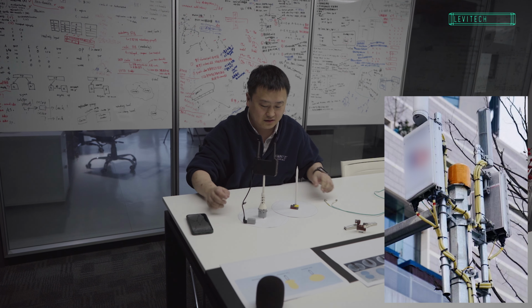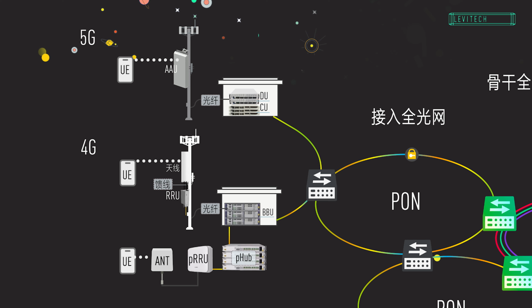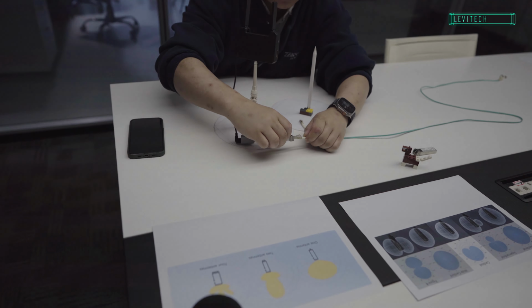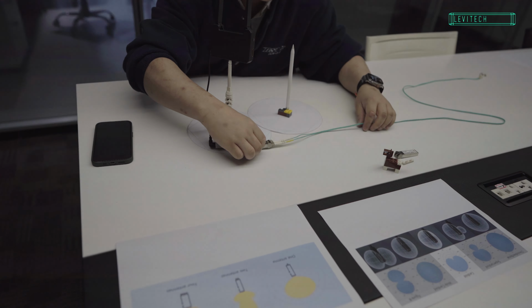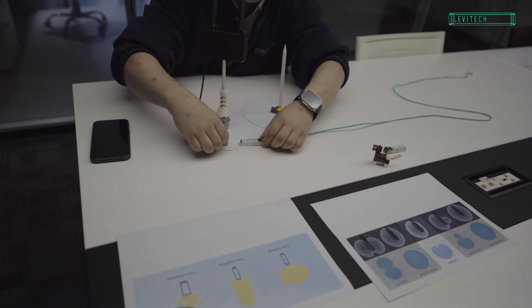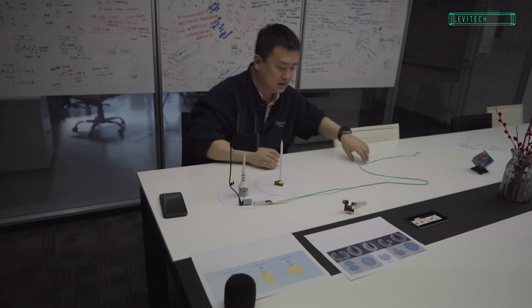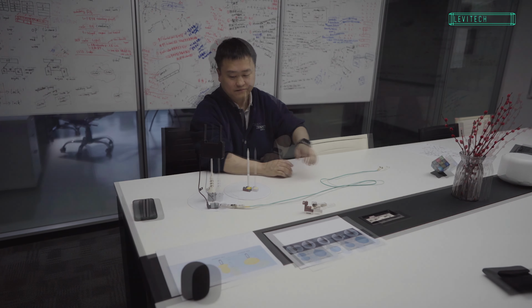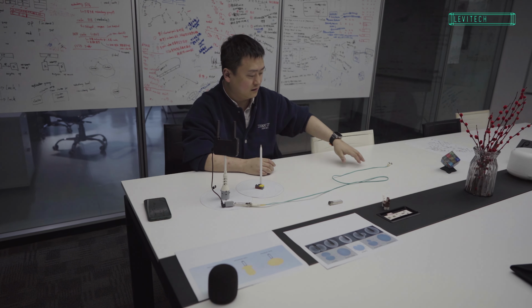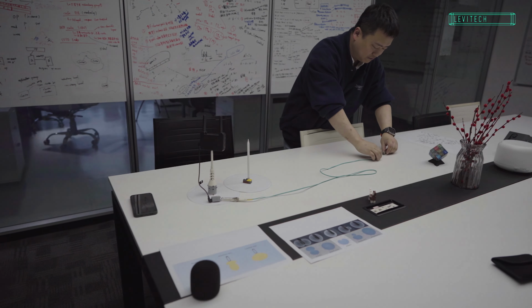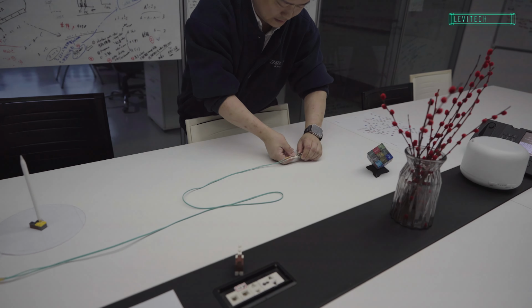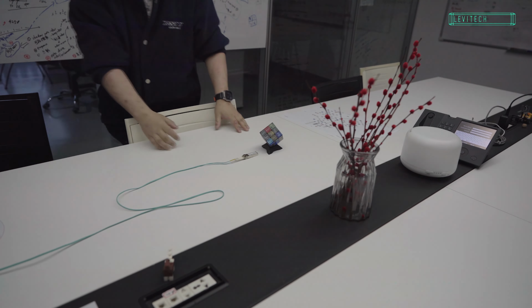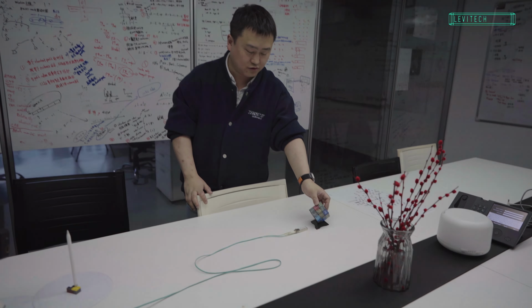The remote radio unit contains optical modules, which connect to a fiber optical cable. In real deployments, this is usually a rugged outdoor fiber cable containing multiple fibers. It runs all the way to optical modules on the baseband unit, commonly referred to as the base station. The antenna and the remote radio units are usually co-located or positioned close together, while the baseband unit can be several hundred meters to over a kilometer away from the remote radio unit.